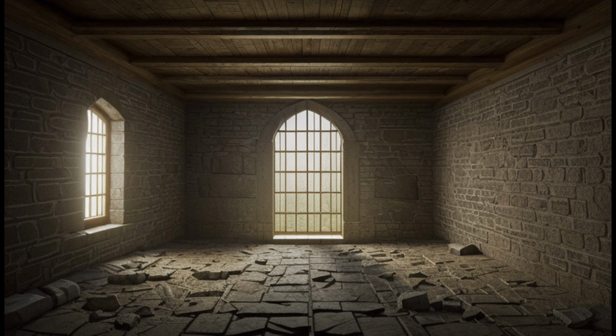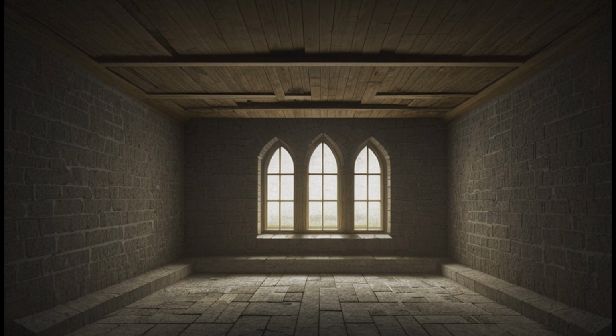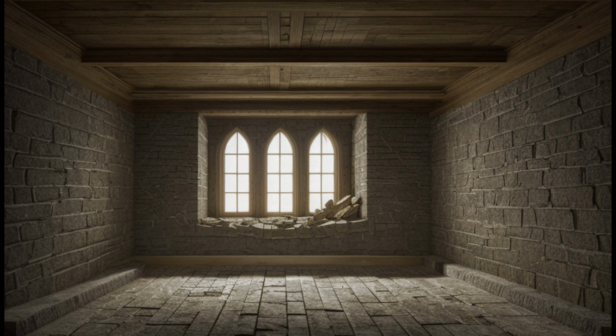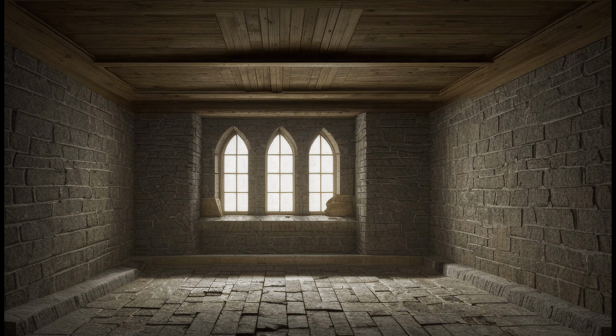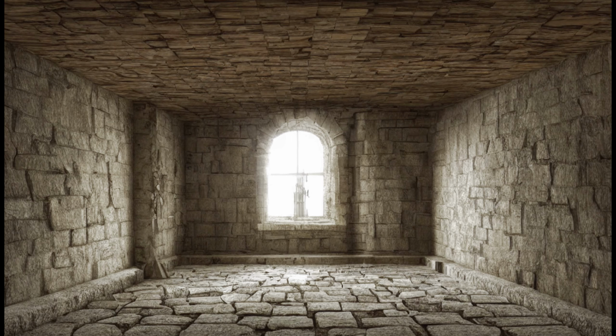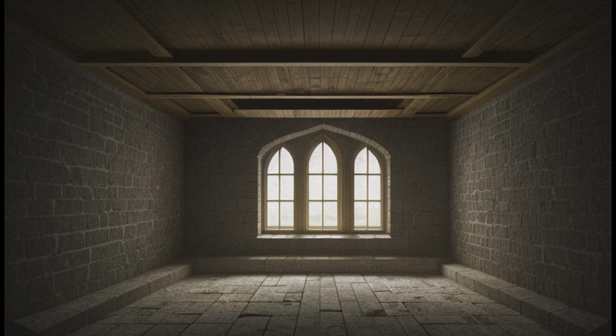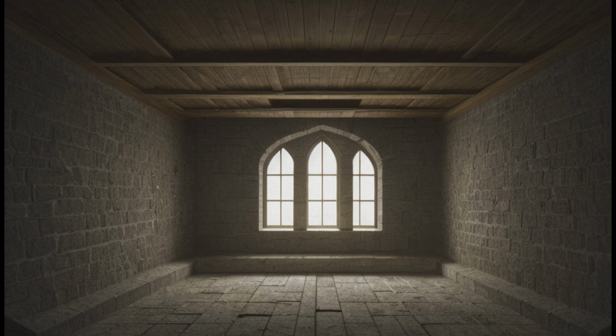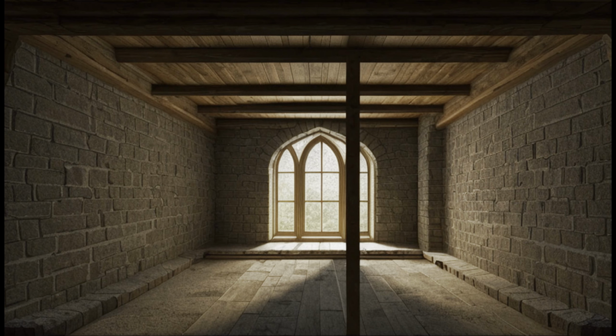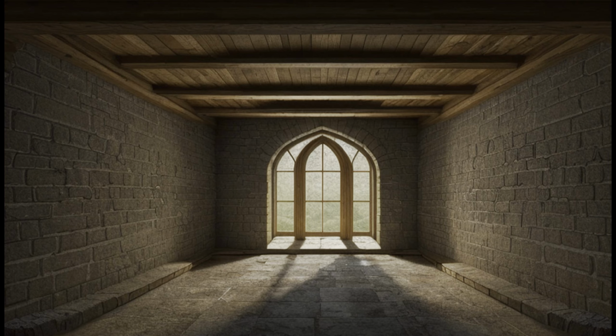Because it does indeed help Stable Diffusion if the edges of the image are not too consistent. And of course, it will be a problem if you're trying to do a rendering animation, because then it will start to go all vague from frame to frame. But in our case, we're just trying to get one nice render out, and our animation will come for free in Blender at real-time speed. Here, I don't know why I got this black line through it. I just had to change ControlNet and regenerate.